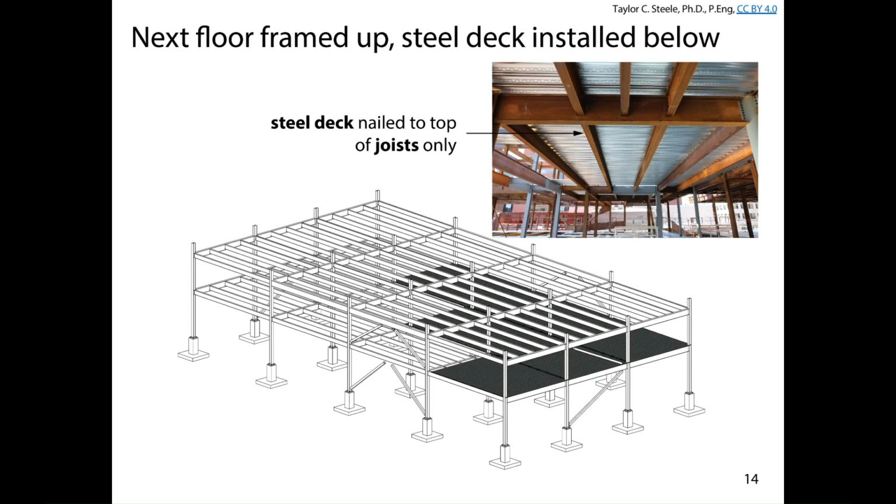All right? So if this was a floor system supported by beams, the steel deck and the concrete on top eventually makes it act as if it's just a rigid plate in space supported by the framing.